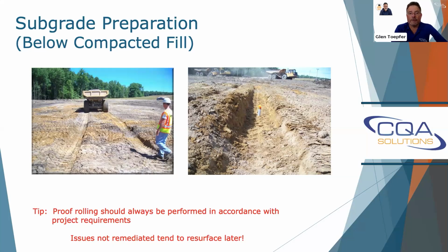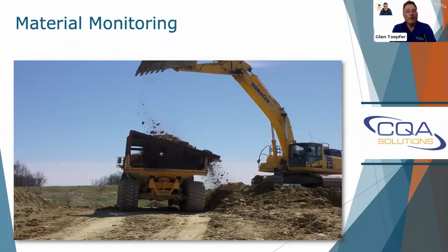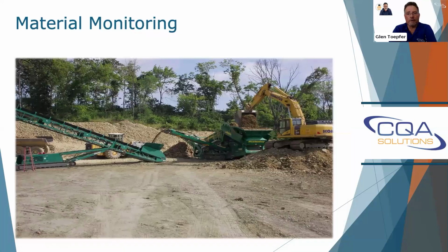Trust me, I've seen people take shortcuts and you're on lift 4 of a compacted fill and everything's starting to pump because you didn't get all the sand seam out or you didn't get all the water out of the sand seam. So things like that happen. Material monitoring, whether it's the borrow area itself or pre-processing, it should always be monitored. Make sure that the material is always in conformance.